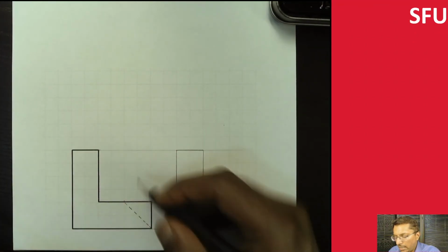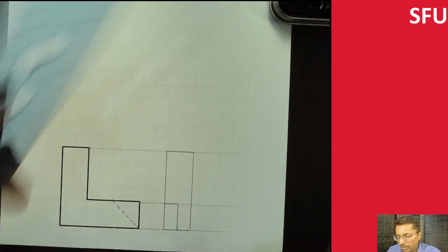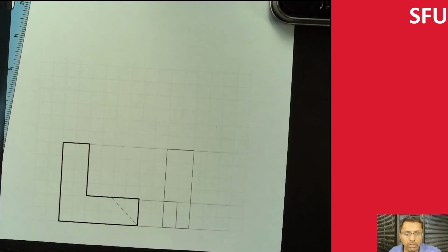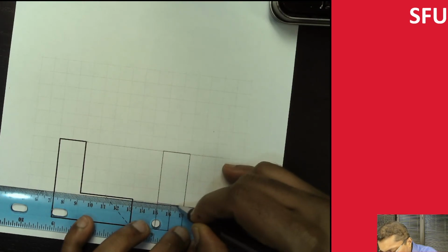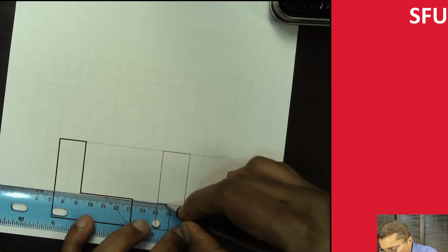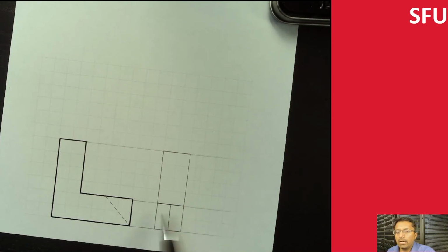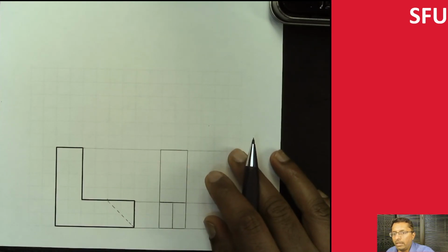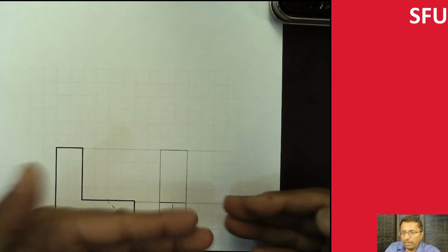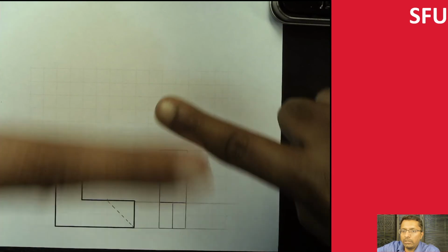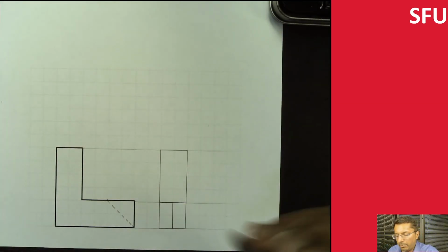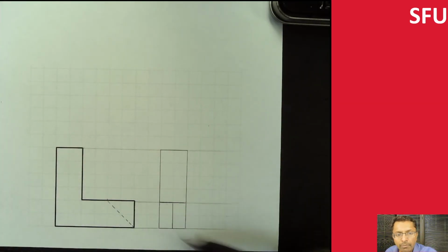And then what I would see then is this edge actually shows up as another half edge over here. What I mean by that is I'm going to create another line here. So in my drawing, this would actually look like a single continuous line, but we have to be aware that these are actually at two different depths. So there's one here, and then there's another one below it. They're at different depths, but because I'm looking at it in this direction, I only see this particular view.